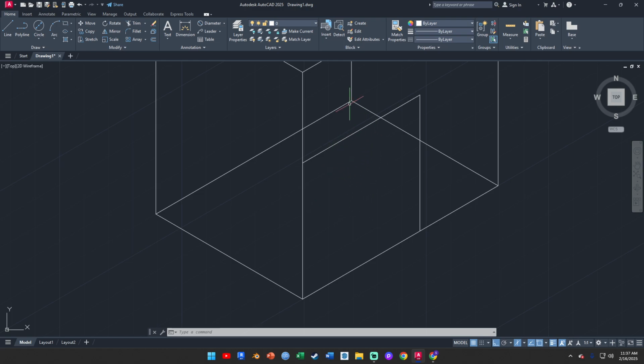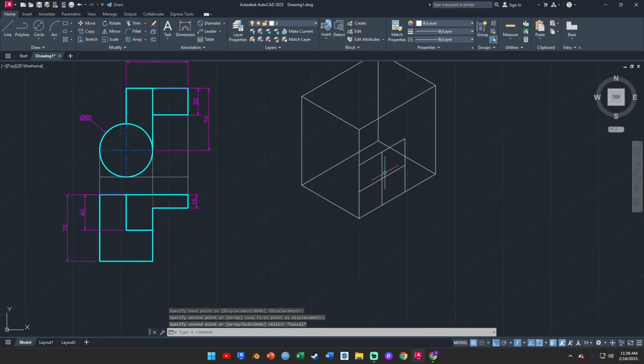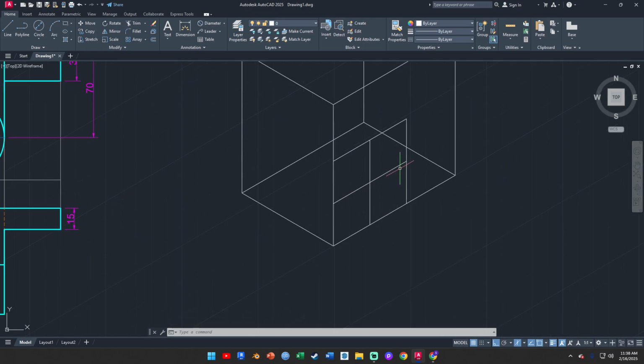And just to get the center now for this isometric square, I'm going to copy this here. Remember, you want to see this symbol here as the center point, right? Or the midpoint. And you repeat the same thing here. Copy, but you don't do it at the bottom, you do it at the top here, right? And it's going to give you the midpoint or the center point. So now we can draw the isometric circle here, right?